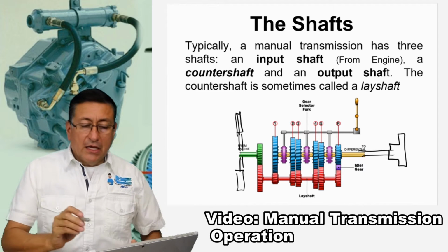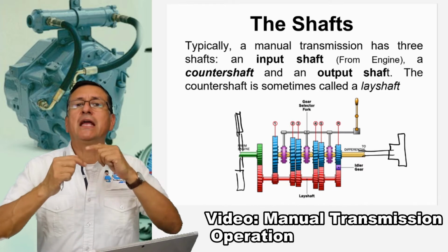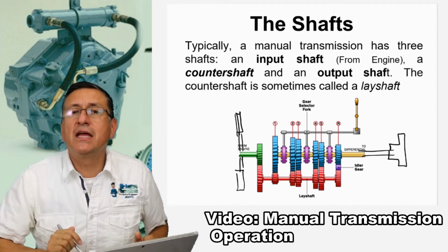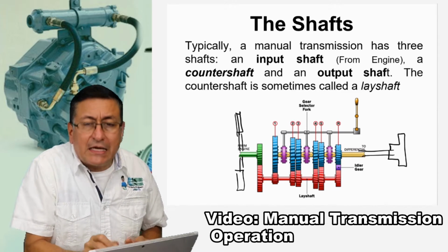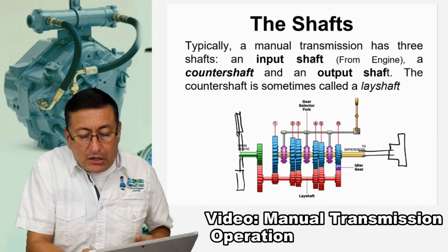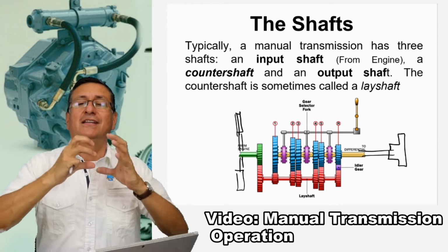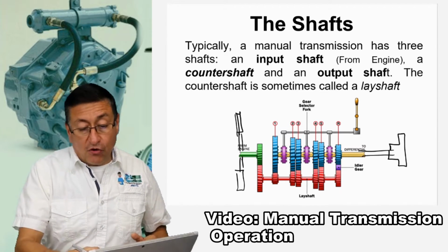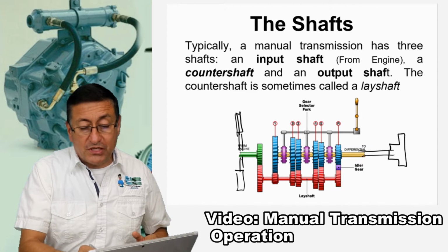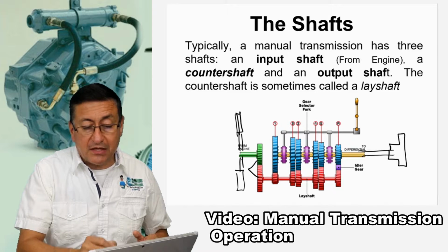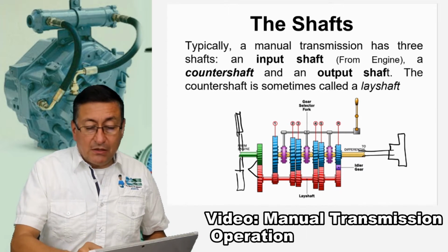And once again, the blue gears in these pictures are spinning free. Only if the purple color with the lateral teeth engages on the lateral teeth of the blue pinions, that pinion engages, and of course engages with the red one, because the red one is always spinning at the same speed as the green. The input shaft is spinning at the same speed as the light shaft.